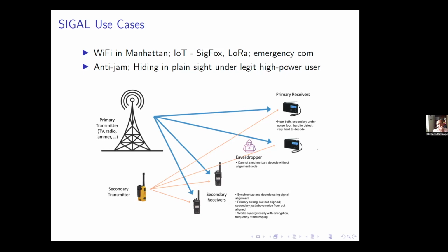IoT communications: as you know, there are now IoT, Internet of Things, sensors deployed all over the world at a very, very rapid pace. And these use protocols known as Sigfox and LoRa for data collection. These protocols actually have built-in repetition for improved reliability relative to fading. Sigfox, for example, transmits every packet 3 times in 3 different hop frequencies for better immunity.